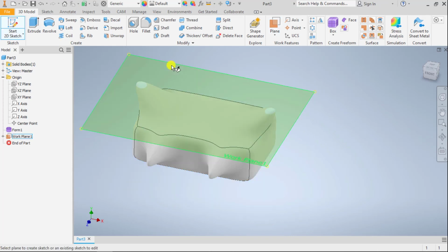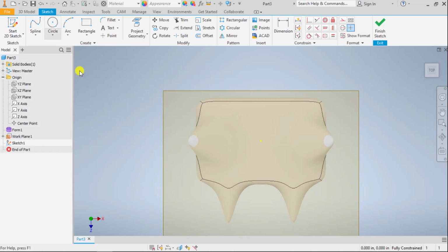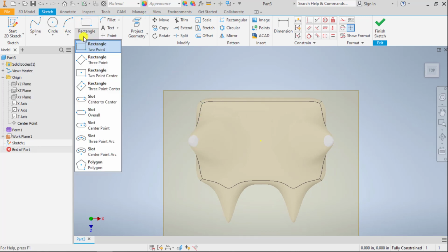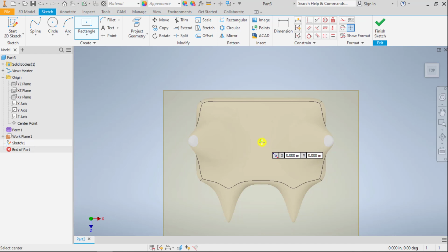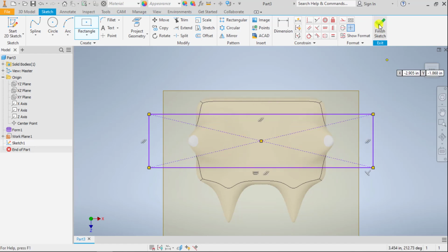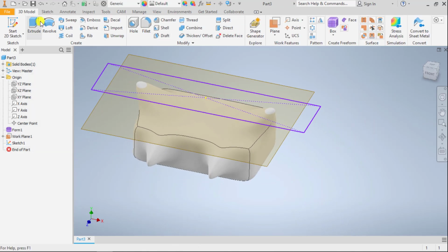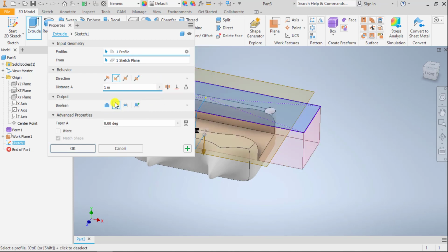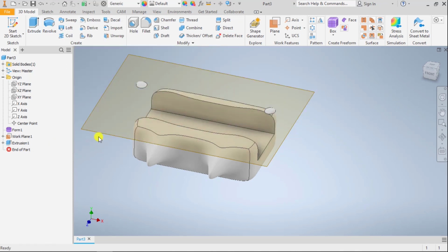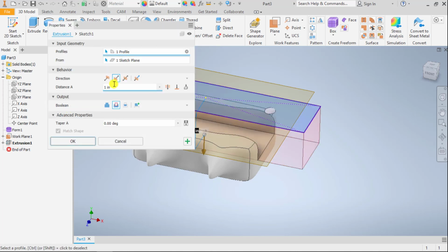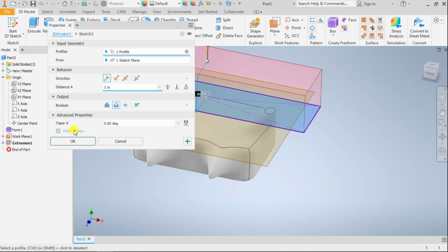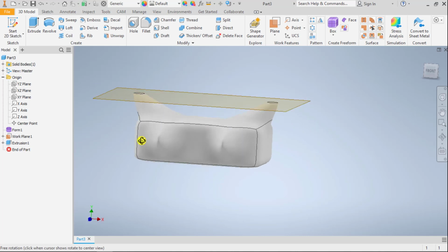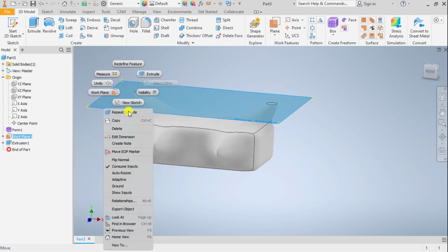And we can do whatever we want. If we wanted to take those points of that extrusion there, and let's say we wanted to delete them, to cut them out, to make a flat, we can come in here and extrude that as a cut, and it went the wrong way. So let's go ahead and flip it. And now I've got that as a flat sitting there.